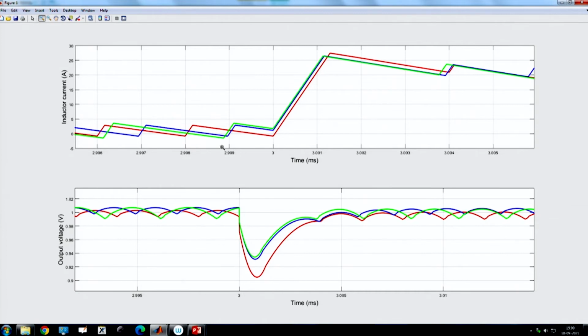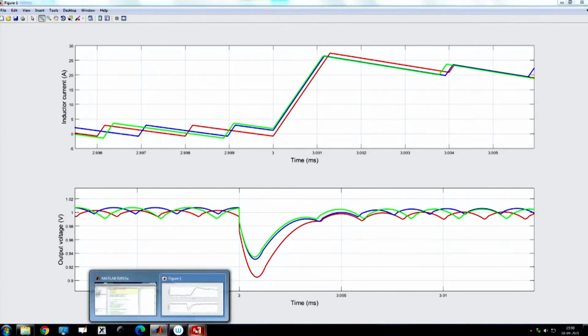But nevertheless, if we apply our tuning rule for first order switching surface and get the optimal slope, and apply the same thing for regular current mode control, then we will get almost time optimal recovery, which is possible using second order switching surface.